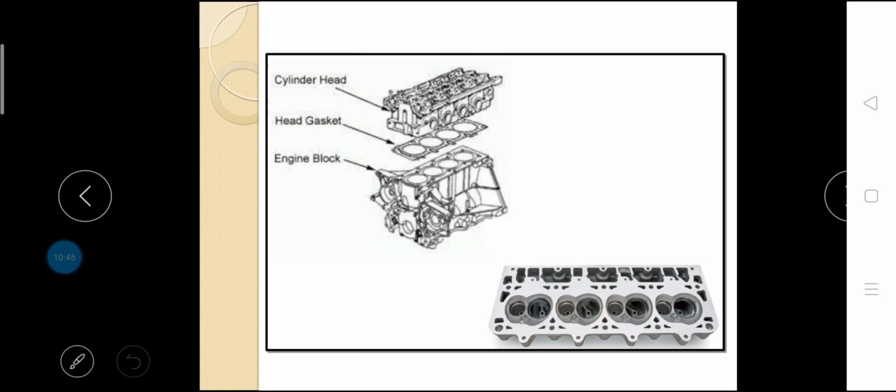Copper increases the hardness and strength of aluminum with time on account of age hardening. However, it decreases the corrosion resistance. An alternative alloy commonly used consists of 4.5% silicon, 0.5% manganese and 0.5% magnesium in aluminum matrix.